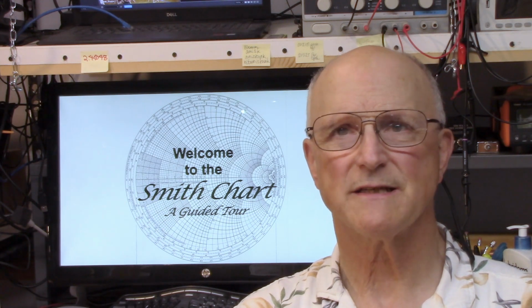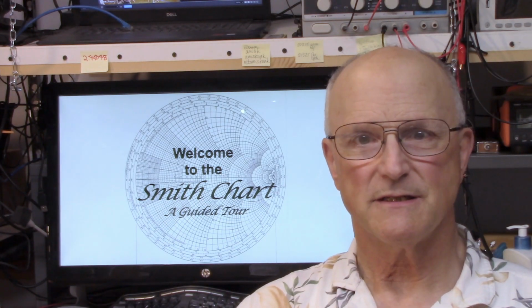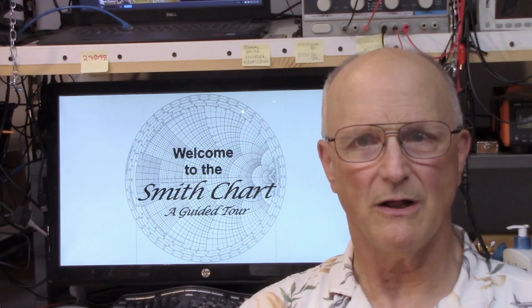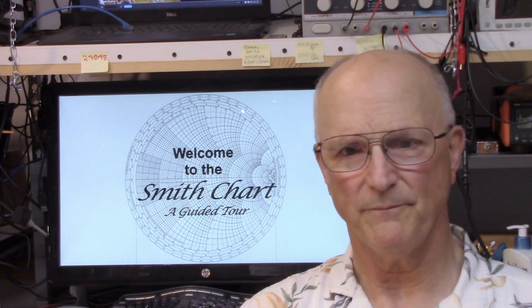To accomplish this task, we used a piece of coax that was 5.2 inches long to transform the load's admittance to one which had the real part that we liked. We then added a stub of coax 8.86 inches long in parallel whose far end was open.